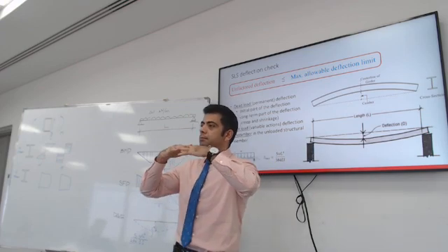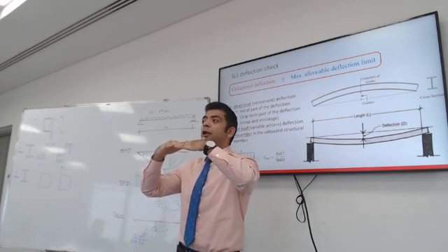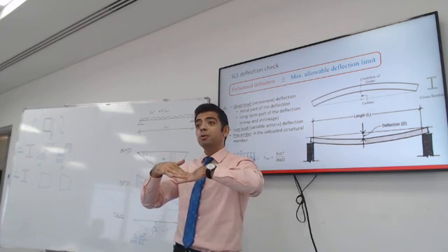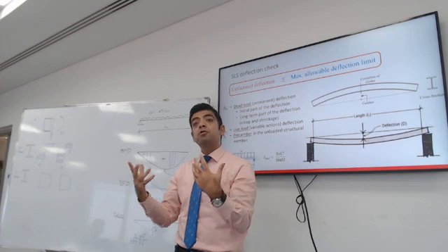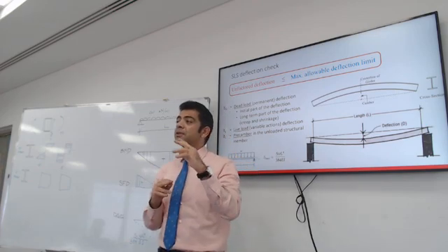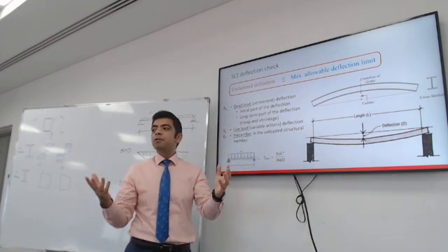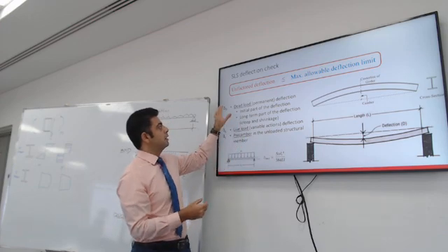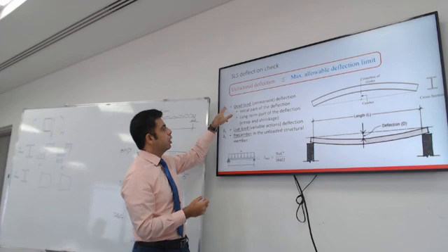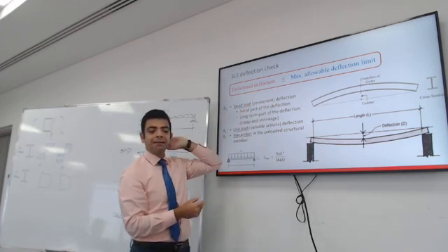With time, the properties of the element could change and could result in what's called long-term deflection. Long-term deflection is usually because of creep and other long-term forces. Some design codes differentiate between the two, but for the sake of our lecture here, let's say this is dead load deflection, or deflection due to permanent loads.